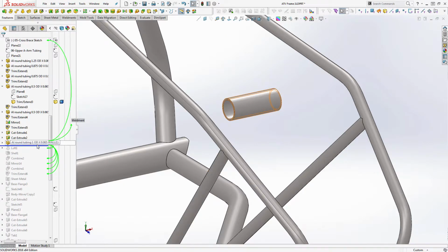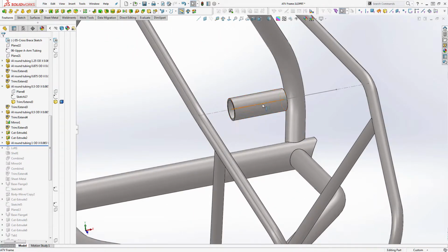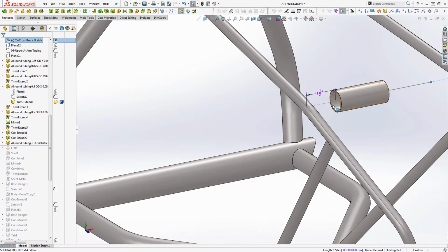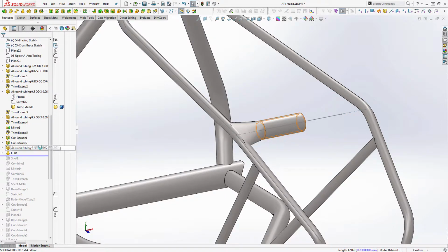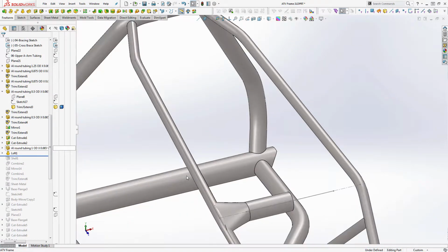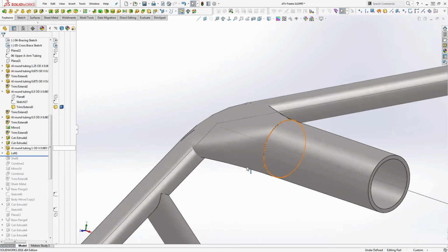So what we did is we had our tube go all the way across, the original sketch, excuse me. I split the line, so I got 2 halves and then 2 areas where we're going to generate the crush or the squash. Generate half the tube, and then we're going to roll down here. Generate the loft. Make sure the loft is inside the tubing so it trims off correctly.